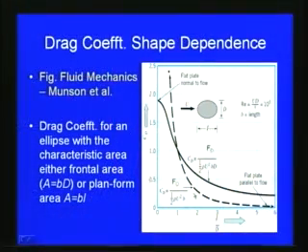For this thick line, CD is equal to Fd by half rho u square into B into D. Here the area is B into 1. This corresponds to Reynolds number 10 to the power 5. Like this we can show that depending upon the shape of the body, the drag coefficient changes.